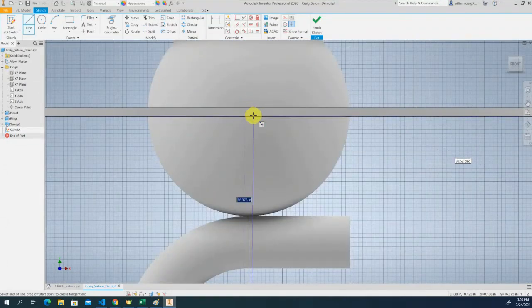I'm going to hit tab real quick. Let's set this to 90 degrees. And now I know that I'm in line. And there's the center point. As I moved up, it turned green for me because again, this comes down to design intent, and I intended that the middle of that axis and the origin point go right through the middle of this. So I can now come up, find that point, and click on it, and it gives me my line. Press escape.